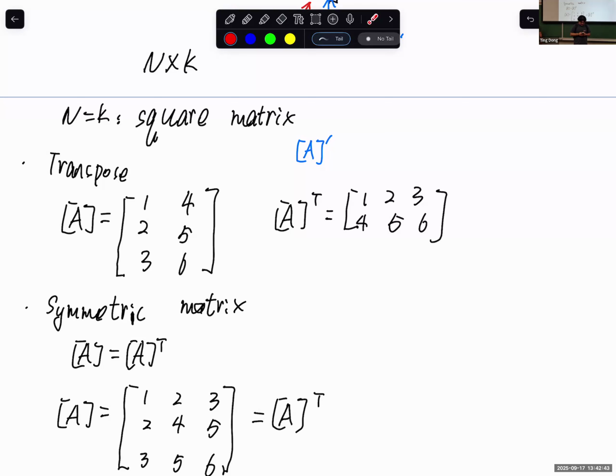Just plot. You have 4 numbers. You use straight lines to connect all those 4 points. So length versus displacement, basically. Yes. The x-axis is this dimension, and the y-axis is the displacement, and you calculate nodes U2, U3, U1, U4, that's 0, use straight lines to connect those and it becomes the displacement field. So it basically means that at any point in the structure, I know what the displacement is. Okay, thank you.